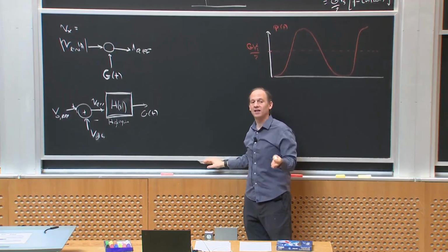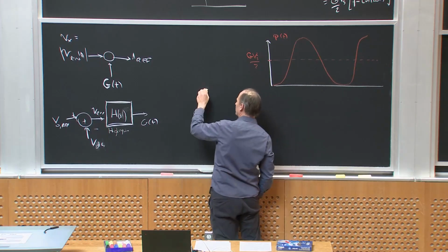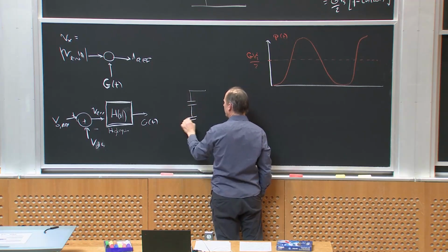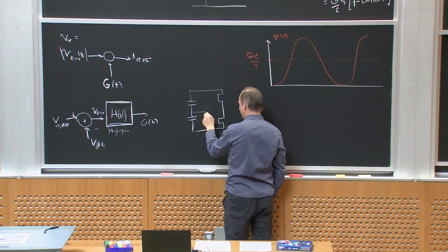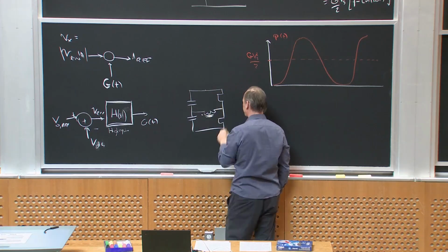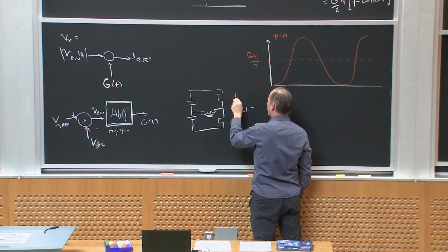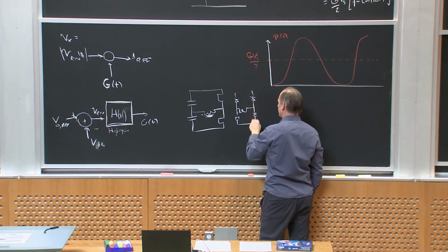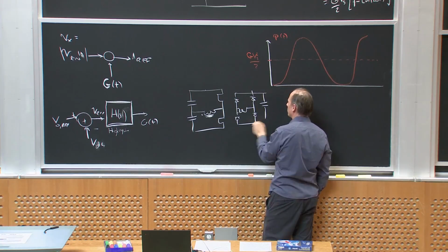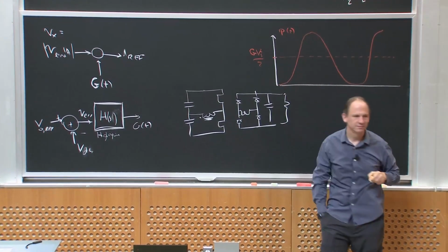It could look like any kind of isolated DC to DC converter we're talking about. It could be just, maybe I split the bus in 2, and I have a pair of switches and a transformer, and then I run the other side of this transformer into a diode rectifier, and that comes out to my 12 volts, for example. And that powers my next power supply.